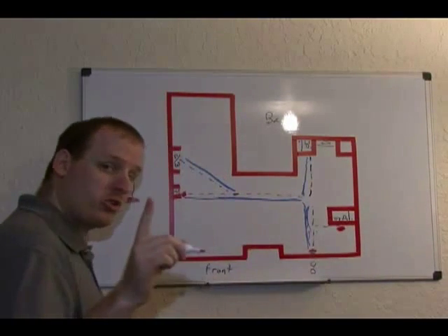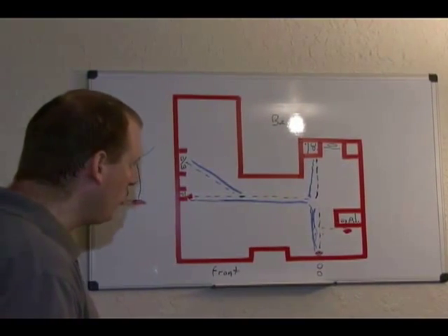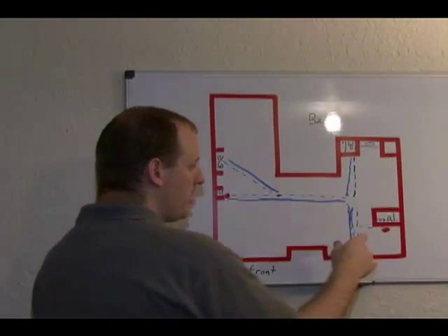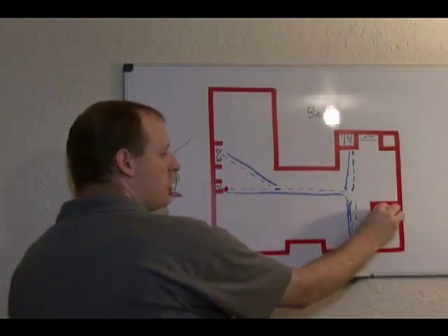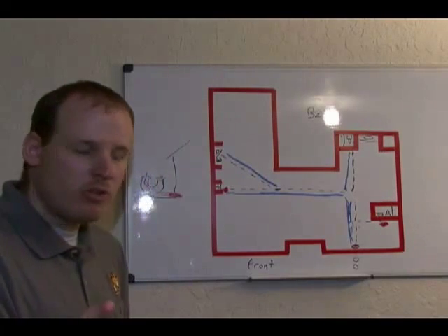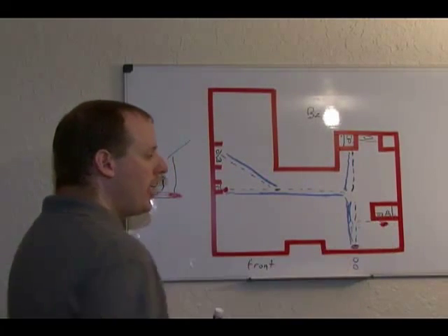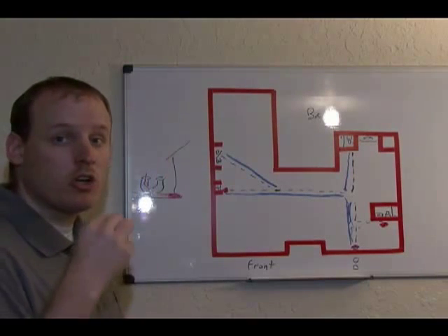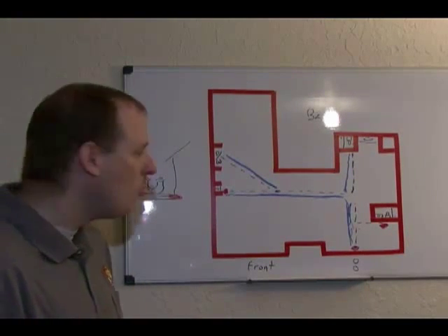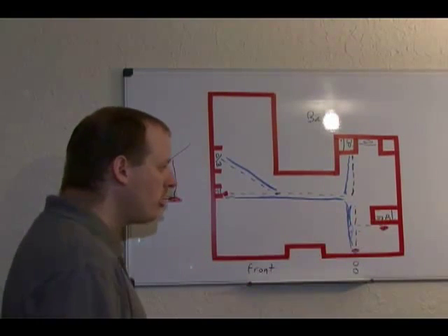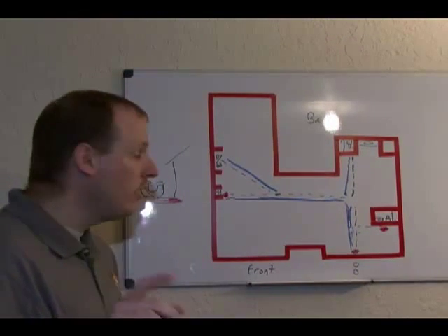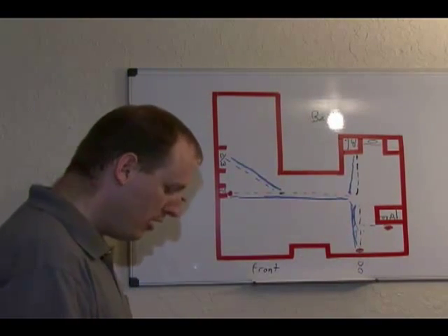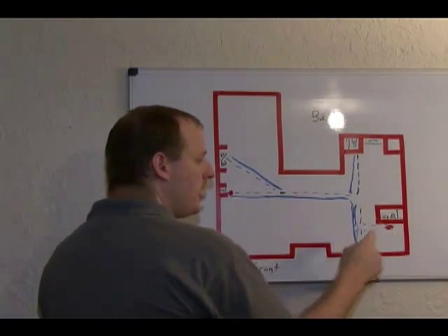And we would for sure do this based on what we know. Okay? This would be our next point of entry. We would place a test ball right here, and we would then test just what's under that bathroom. At that point, you are testing basically the commode and the tub in that bathroom. The lavatory goes into the wall, so we're not even testing what's in the wall there. You would test just the lavatory and the commode. Because of our pre-information, we know that there is a leak in that area. So we would then determine that there is a leak here.